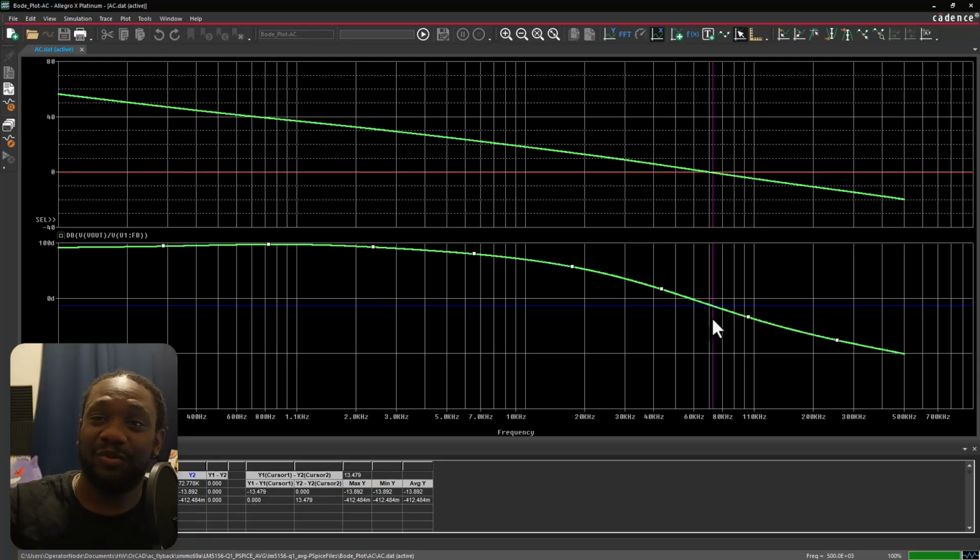That's not great. In extremely short amounts of time, that's going to blow up your converter, or overstress it, or make it get extremely hot and possibly blow up. So that's why we totally want to stay far away from 180 degrees.